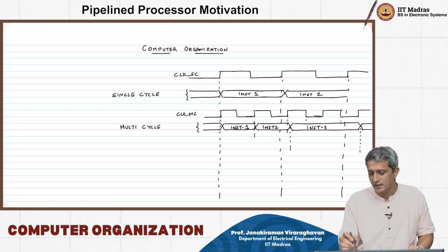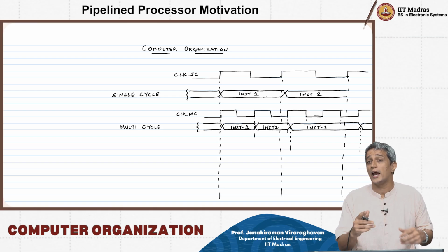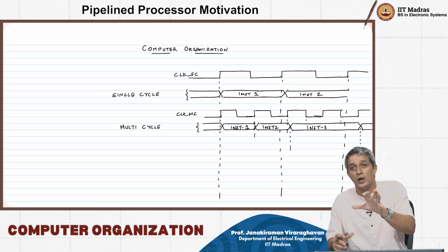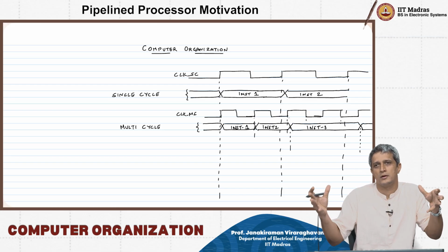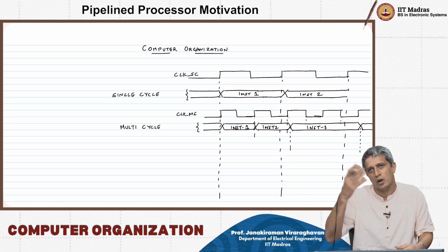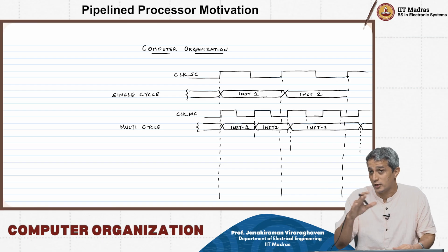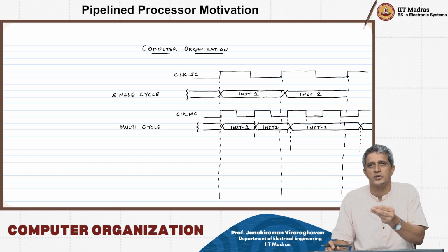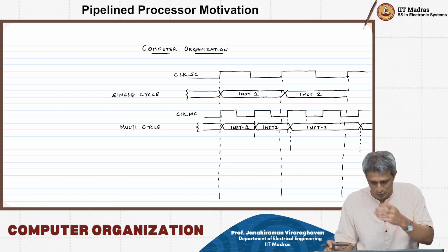Okay, again this instruction 1 and instruction 2 can execute in a single cycle only if you fetch, decode and execute in one shot. Okay, only the register write back or memory operation can be separated out. Okay, only then at least that R type instruction or something can be executed like this, right?